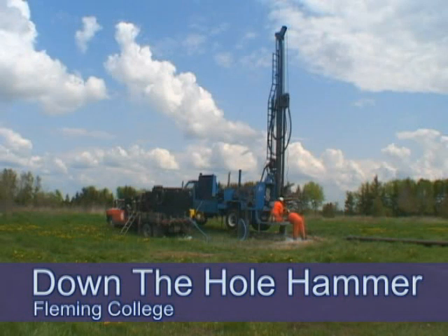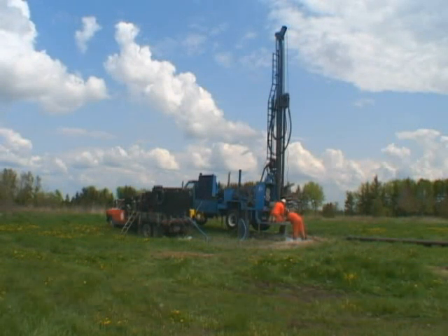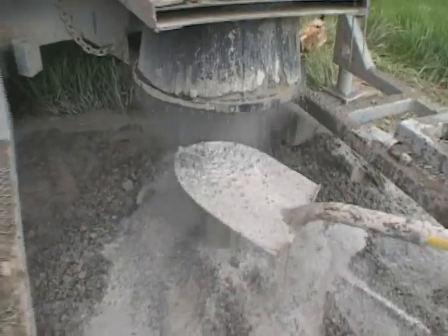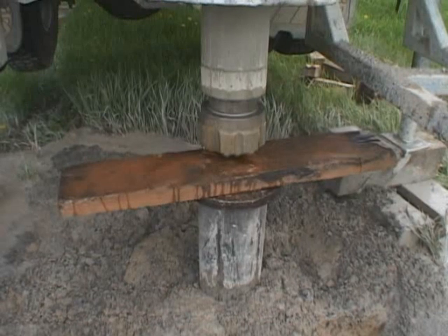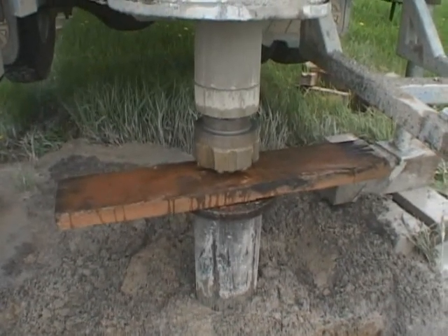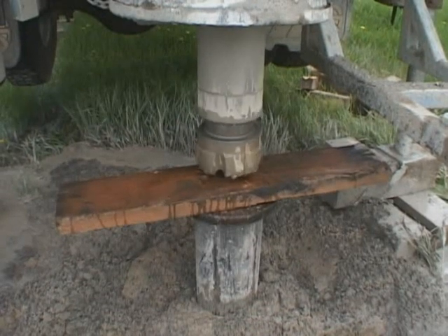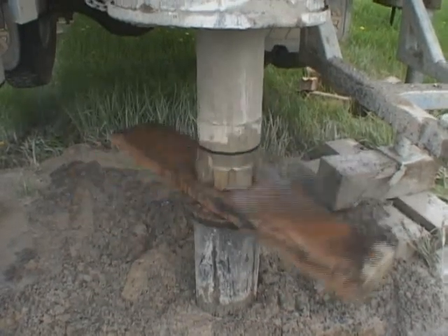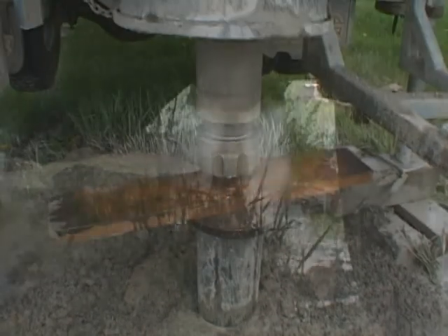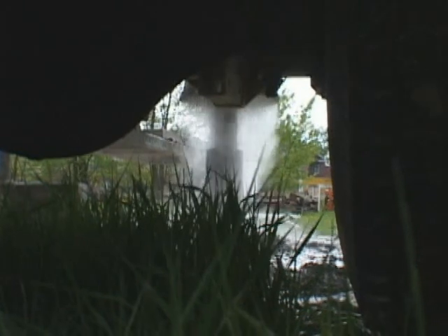The differences between the air rotary system and this drilling system are primarily the cutting action and the resulting cuttings as shown. The down-the-hole hammer uses the rotary percussion cutting action through the use of a button bit. This system is best suited for well-consolidated formations, offering excellent penetration rates. Compressed air provides the percussive energy to power the hammer. The resulting exhaust removes the cuttings.